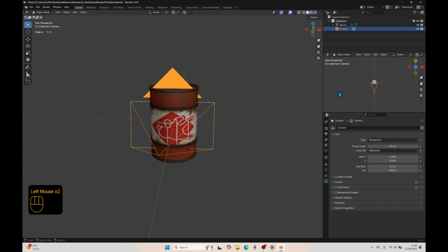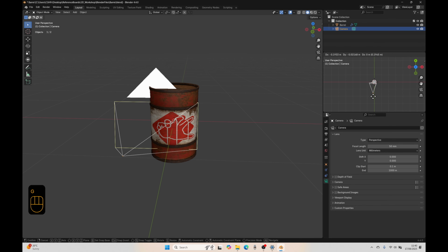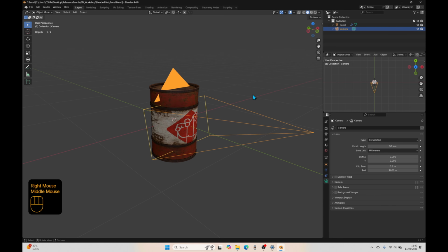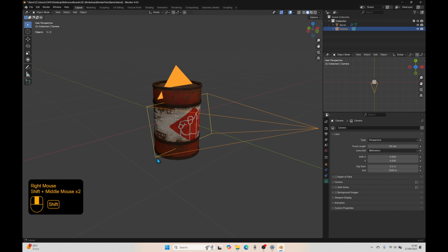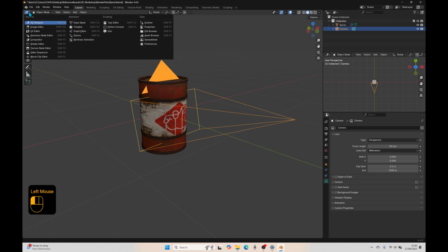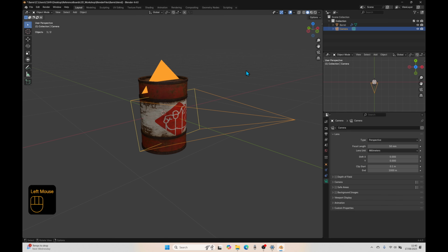And there's lots of ways you can move this camera around. With it selected, I can hold G to grab it, and we can move that around. We can do it in this scene. Or there's a really handy way to maneuver around your viewport. And if I just press Q, you won't necessarily have this. You can see that opens up our quick favorites menu. And you can save anything you want here as a quick favorite. So anytime you're in this viewport, specifically the 3D viewport, and I press Q, I have these shortcuts.